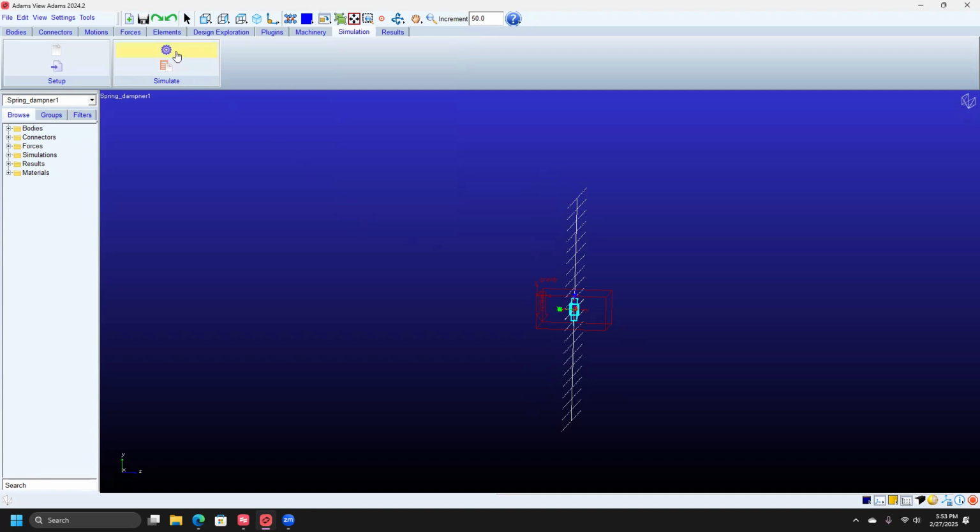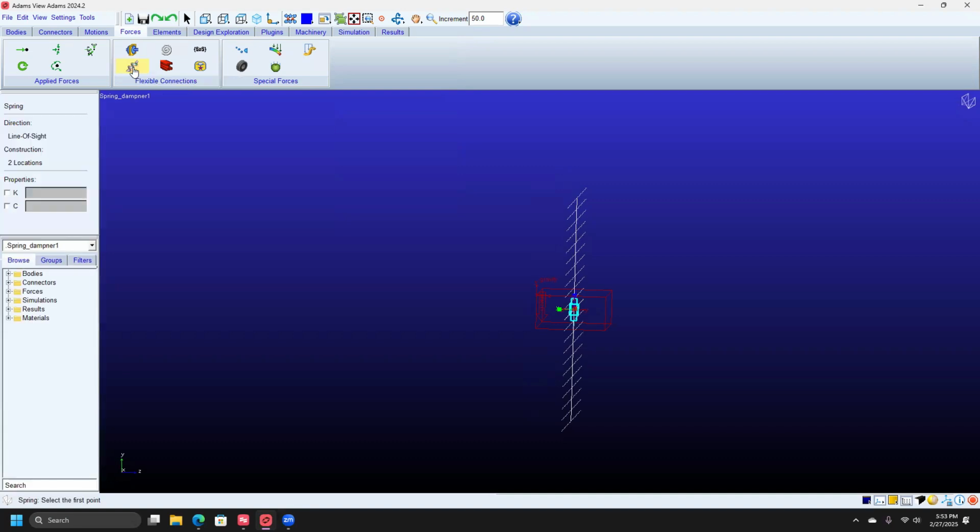So now we're going to want to add a predefined spring damper. We'll do this by going here. As we can see, under flexible connectors, it has a translational spring damper, excuse me. We're going to want to go ahead and select this. Then for our properties, we'll select both K and C. We want to set our K value to 5 and our C value to 0.05. Or for whatever project you're using, you'll want to set these to whatever spring you're using.